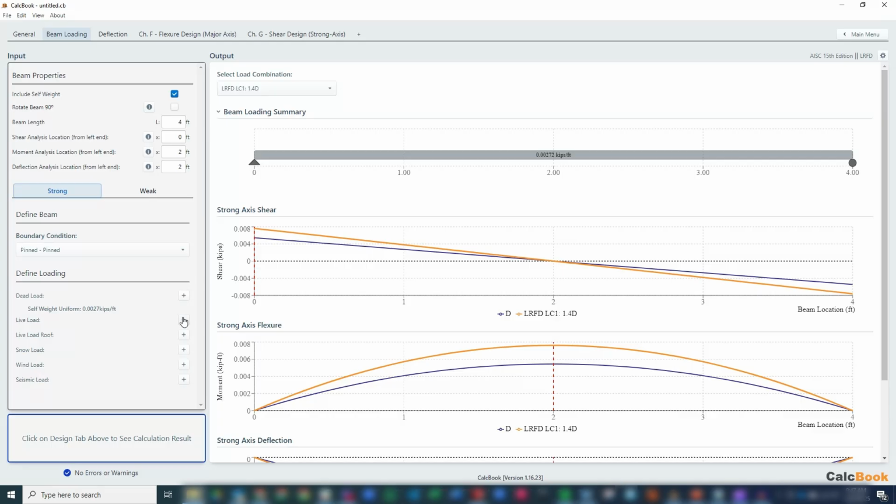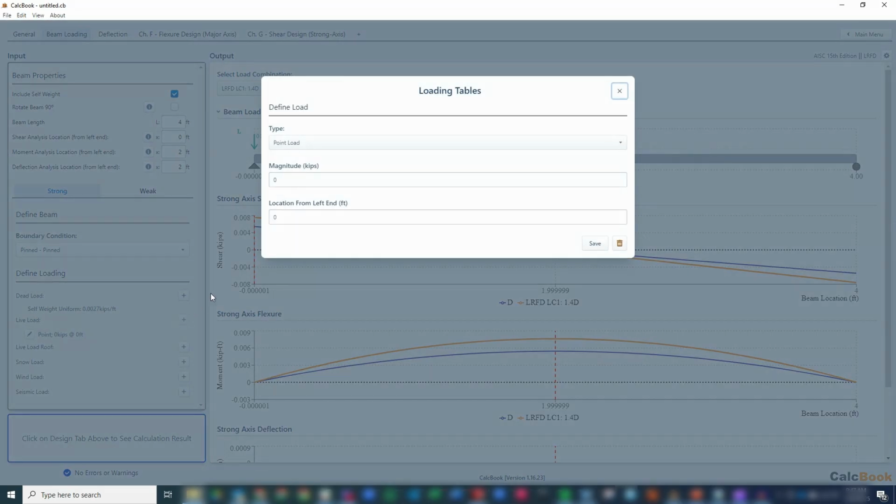So let's go ahead and enter in our live load. The handrail is a live load, so we want to make sure we do that. And in the problem statement, we showed a distributed load at 50 pounds per foot, but actually, it's a 200-pound point load or the 50 pounds per foot. And in this case, a point load at the midspan is going to result in a larger moment. So we'll go ahead and use the 200 pounds point load, midspan,